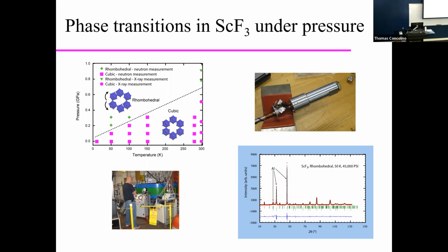And you may say, well, 1,000 atmospheres is high pressure, no big deal. Actually, it's not. You can generate 1,000 atmospheres pressure on something easily. Just take a pestle and mortar and grind. That's the kind of stress levels you get, or actually higher. So these kinds of low pressure phase transitions you can generate in composites due to one material expanding and contracting.